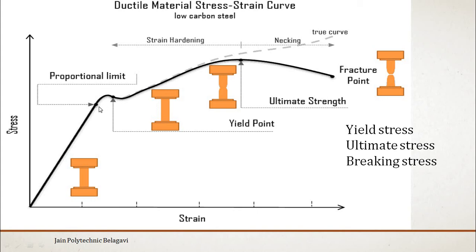It is not going to be in proportion. Okay, so till this point, consider this to be the proportional limit point. Thereafter, again the load is increased, which means stress is increased, and you are finding there is also an increase in the length or deformation or strain, right?